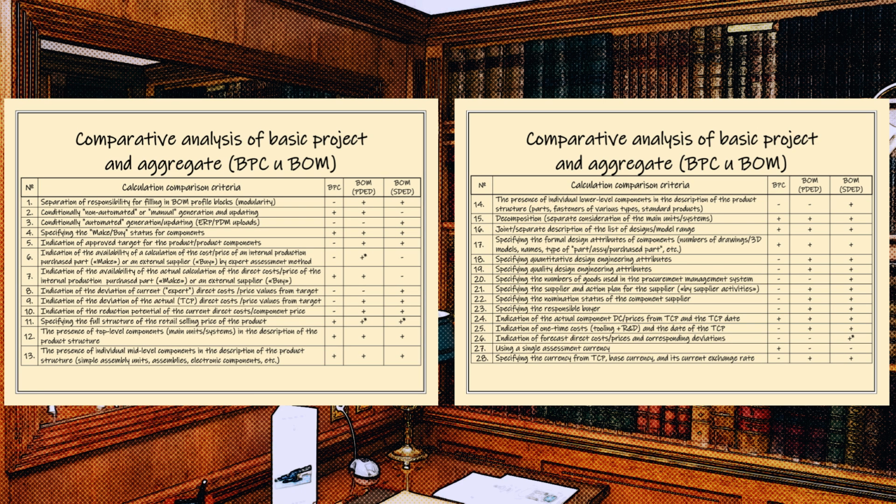If we talk about practical examples, then we can consider the example of stamping a sheet part. Prototype tooling stamp, as a rule, is made from aluminum alloy and has an insignificant resource, about 500 to 1000 strokes. In addition, aluminum tooling can be modified for relatively little money in accordance with the changes in details during the design engineering documentation modification at the stages of the preliminary and technical design engineering. Stamping tooling for mass-produced products has a significantly longer service life. Depending on the series, it's made of steel.